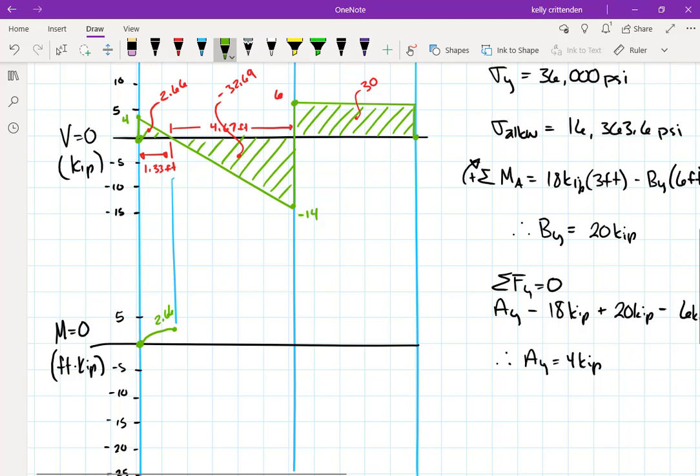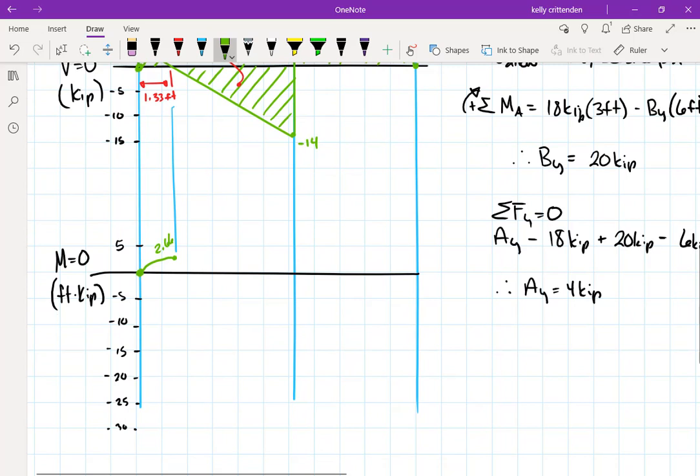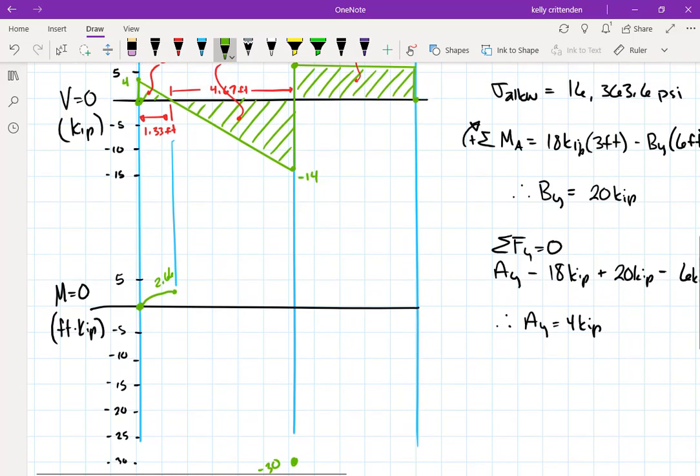We're going to subtract off 32.69, so down to -30.03, which is why I wanted to get way down to here, negative 30. And this one starts at 0 shear in my shear diagram. So that means it's horizontal, and then it gets larger and larger values of shear. So that means the slope in my moment diagram gets steeper and steeper. So maybe something like that.